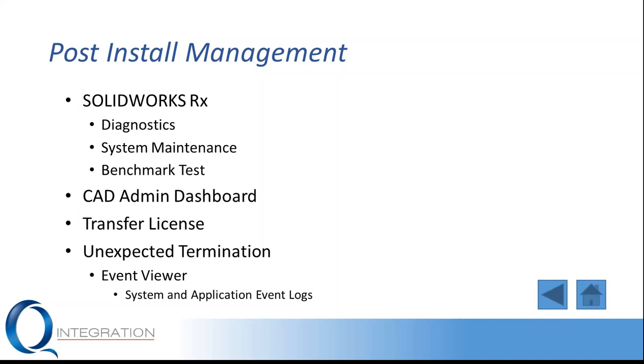And the SolidWorks RX tool is designed to help us do this, utilizing the Diagnostics tab to take a look at some of the system resources there, as well as the System Maintenance tab, where we can go through and do simple maintenance on these machines, deleting files from temp directories, running defragmentation for the disk, whatever it may be. We can also utilize benchmark tests to see where we may have bottlenecks on a particular user's machine.